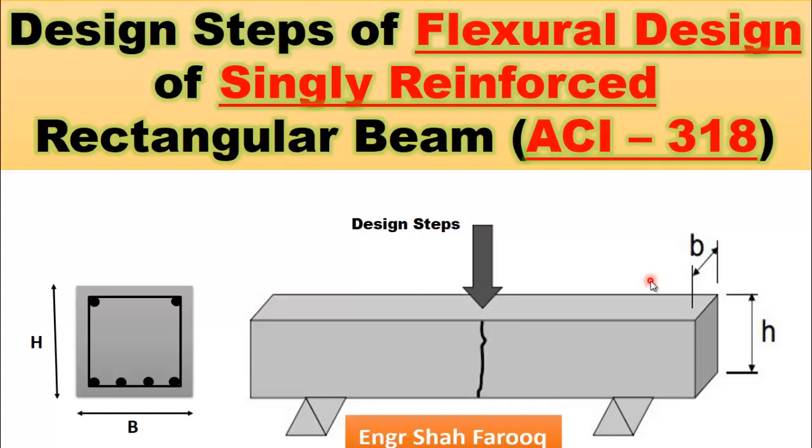of reinforced cement concrete. Flexural design of beam means to design a beam to resist bending moment developed due to the applied load. In design of beam, we select the cross-sectional dimension of the beam and determine the required amount of steel reinforcement to withstand the maximum bending moment developed in the beam due to applied loads. In this particular video lecture, we will cover the steps to be followed for flexural design of singly reinforced rectangular beam. Singly reinforced beams are those beams in which steel design is only carried out for one side of the beam. For most cases, it is the bottom side of the beam.